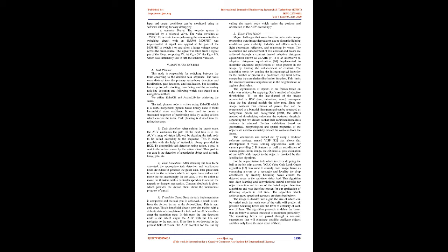We utilize SMACH and ActionLib for achieving the same. The Task Planner node is written using SMACH, which is a ROS-independent Python-based library used to build hierarchical state machines. It was used to create a structured sequence of performing tasks by calling actions which execute the tasks. Task planning is divided into the following steps.